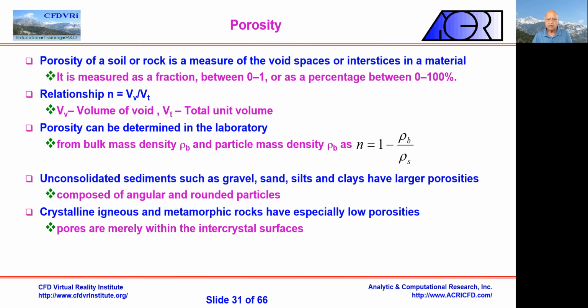Now, no water can go through the solid, it can only go through the porous component, right? Okay, so the porosity is between 0 and 1, and more porous means, for example, big pebbles would be more porous, sand, smaller grains would be less porous, the porosity would be smaller, okay? So the porosity basically is the volume of the voids to the total volume, okay?